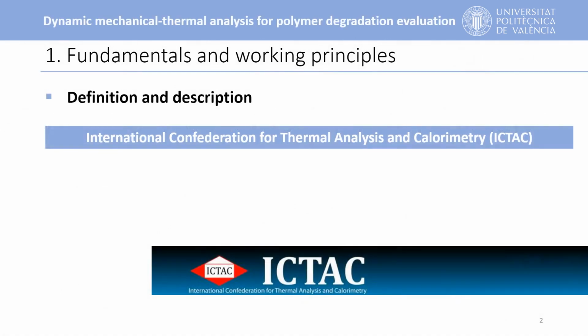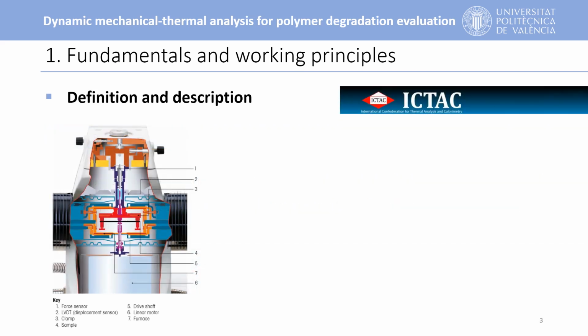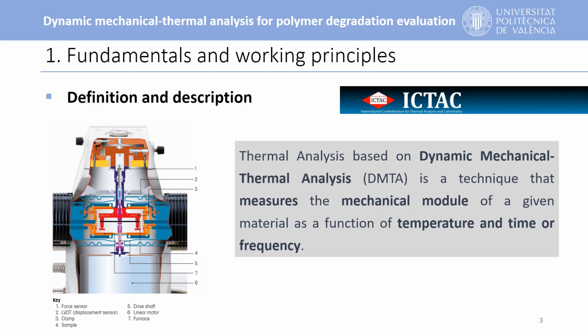We will start by defining thermal analysis as a set of experimental techniques by which a physical or chemical property of a material is measured as a function of temperature, as established by the International Confederation for Thermal Analysis and Calorimetry. Particularly, dynamic mechanical thermal analysis is defined by the ICTAC as a technique that measures the mechanical modulus of a given material as a function of temperature and time or frequency. The response of the polymeric material to a mechanical disturbance gives information about its structure.